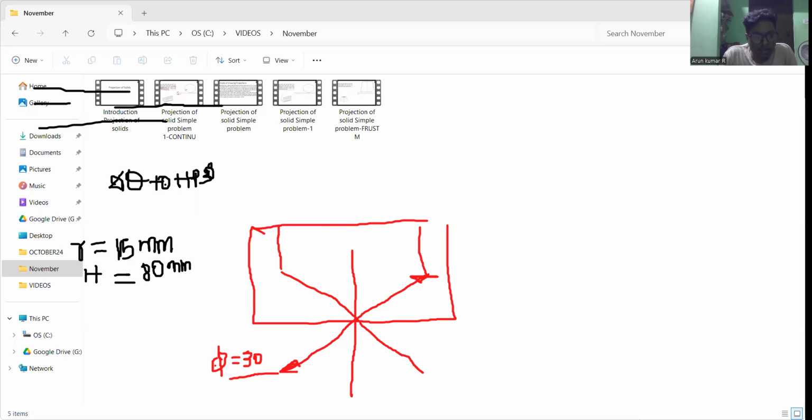First, after the projection line, you have to draw the baseline, from start to end, that is a dash to e dash. Next, take the 80 mm height here, and also here, and close this box.